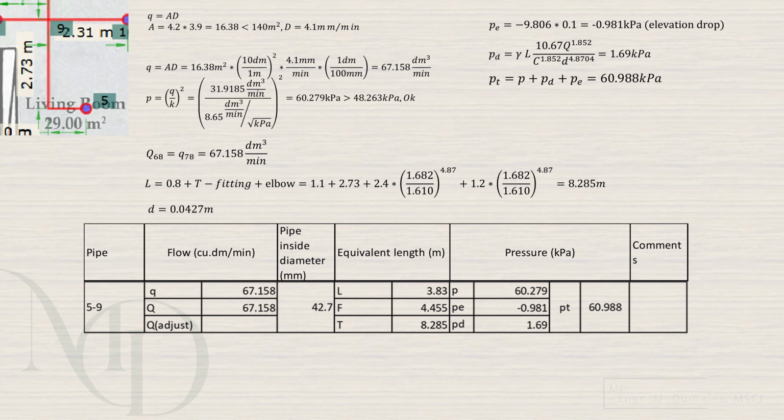Remember that lowering the sprinkler reduces the required pressure, so we add or subtract the appropriate PE term in the pressure demand computation. After that, we plug the total discharge and the effective length into the pressure drop formula and solve for the pressure loss. Add the pressure drop to the pressure demand to get the resulting pressure at the downstream node. With all values computed, tabulate the results.